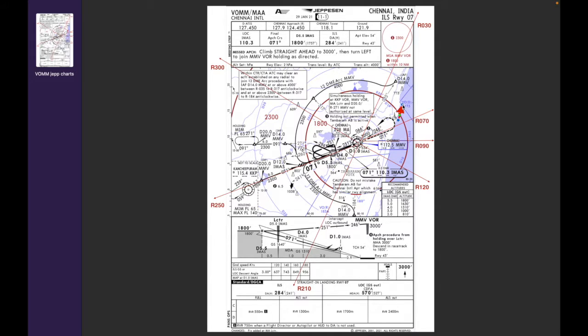And obviously you can't fly 030, right? You can't turn left and just fly 030 because then you'll fly parallel to the VOR, parallel to this radial, right? So you can't fly the same heading. You need to fly an intercept heading. Now, what would the intercept heading be? A simple rule of thumb is just subtract 30 degrees from the direction that you want to go. So in this case, 030 minus 30 degrees, 360 degrees, is a very good intercept heading.